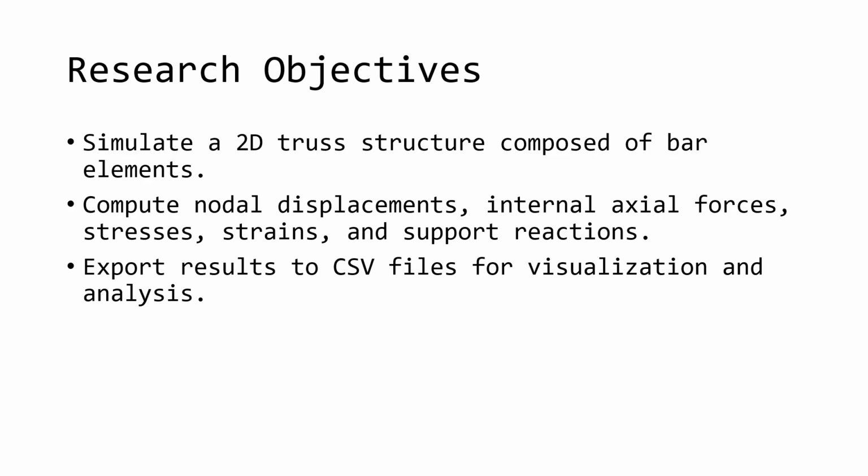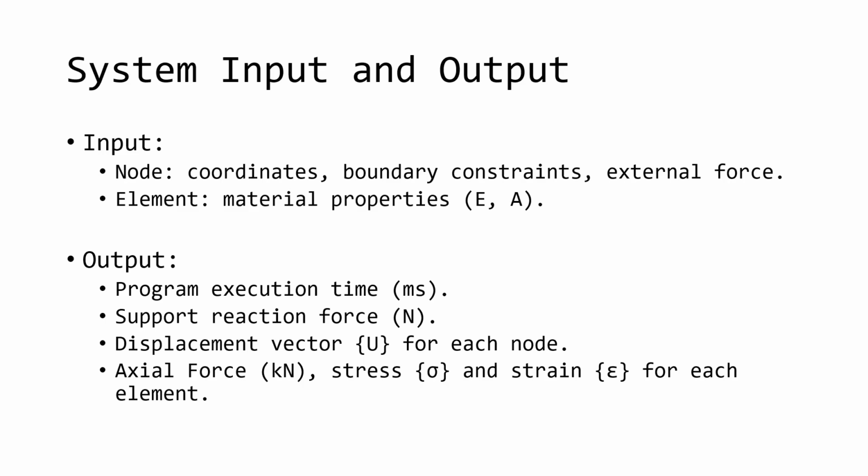To improve performance, we implemented a parallelized solution process. Inputs include node coordinates, boundary conditions, and applied external forces. Element data includes material properties, such as Young's modulus and cross-sectional area. Outputs include execution time, nodal displacement vectors, element internal forces, stresses, strains, and support reactions.